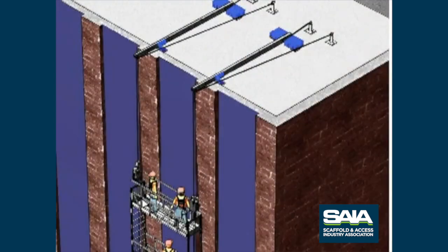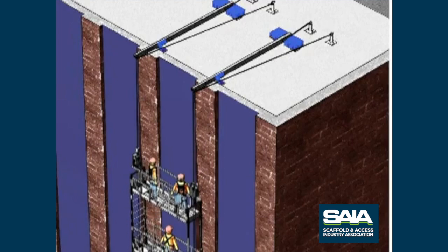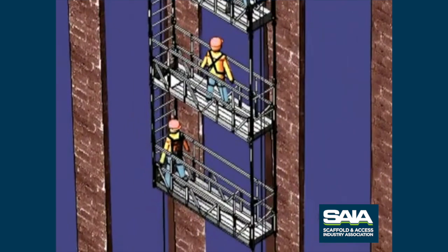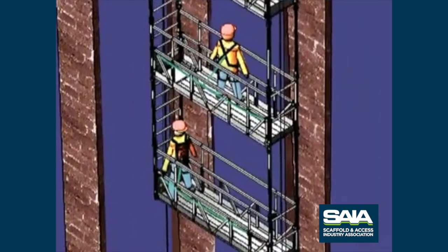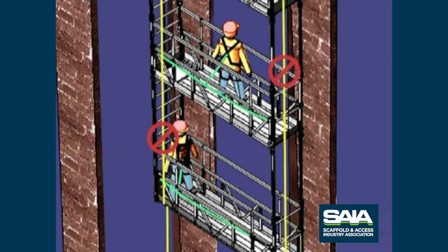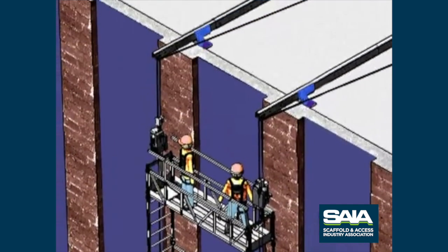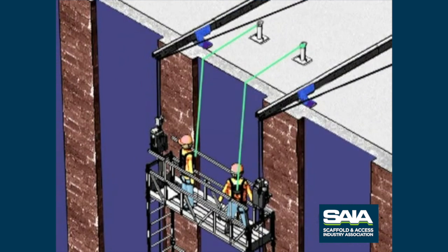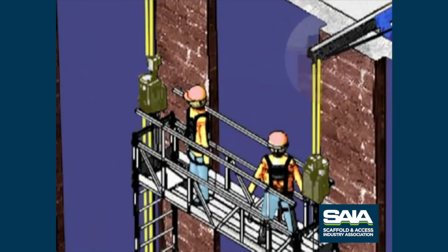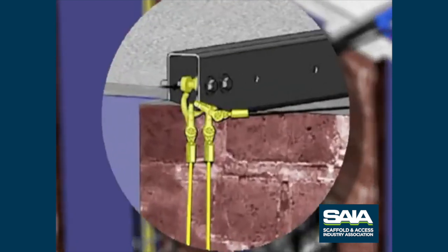When using a multi-tiered swing stage assembly or a single stage with overhead protection, workers on the lower stage or stages must secure their lanyards to a structural part of the stage itself and not to an independent suspension line. Workers on the top level can use a lifeline if the stage does not have overhead protection. Hoists must be rigged with primary and secondary wire ropes attached to separate points of anchorage.